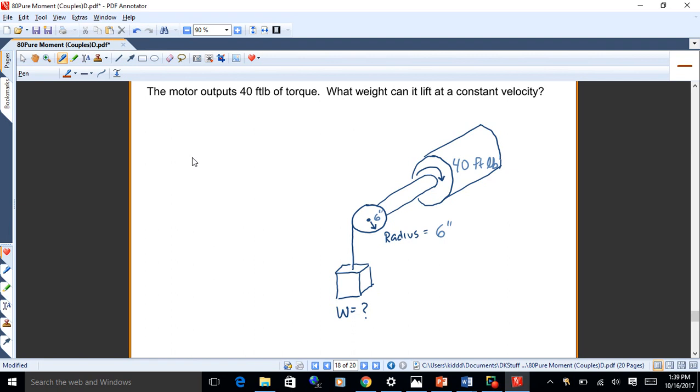If you look at trucks, they talk about the torque they generate. Same sort of idea: the moment coming out of the engine on the drive shaft. But they talk about torque and power, right? Torque is just the moment coming out of the drive shaft. Power is the moment times the angular speed, converted from RPM into radians per second. Yeah, the angular speed that you use multiplied by the torque.